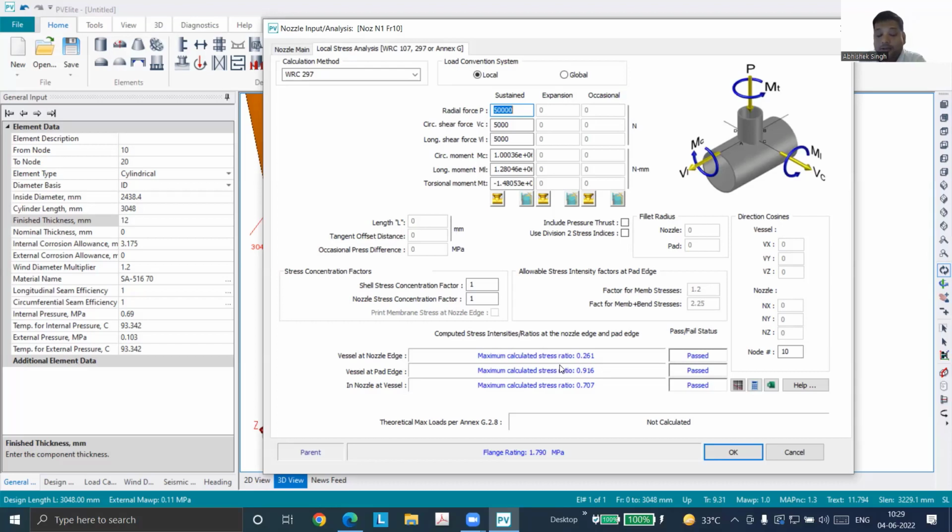You might have seen gussets only for smaller size nozzles, normally for 2-inch or very rarely for 3-inch. Mainly for 2-inch, you'll see gussets, or we call them stiffeners, attached to that nozzle. What do you think may be the reason for that? The nozzle section is very less to withstand the bending. It's a cantilever condition, no?